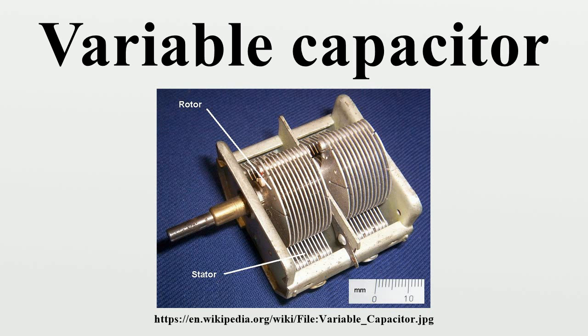A vacuum variable capacitor uses a set of plates made from concentric cylinders that can be slid in or out of an opposing set of cylinders. These plates are then sealed inside of a non-conductive envelope such as glass or ceramic and placed under a high vacuum. The movable part is mounted on a flexible metal membrane that seals and maintains the vacuum. A screw shaft is attached to the plunger.